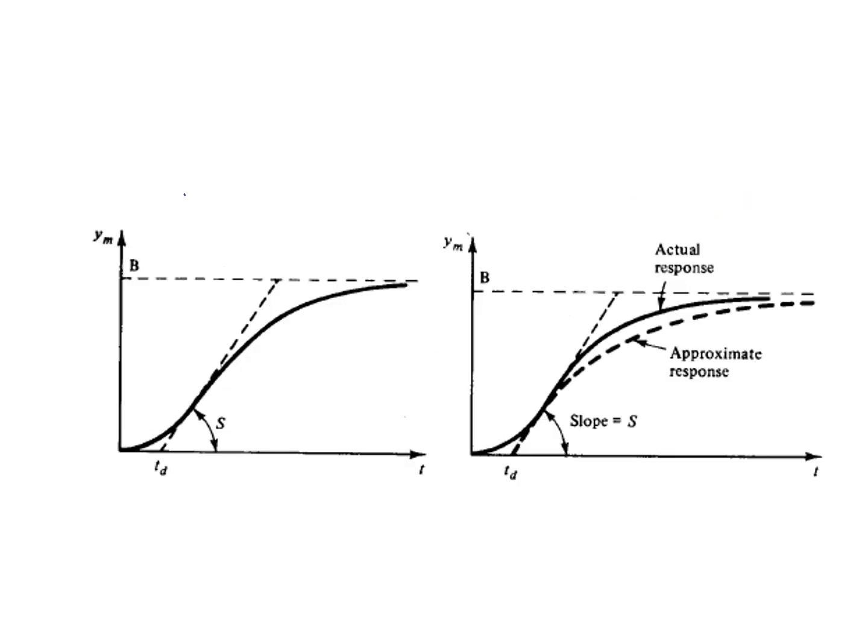So this is your PRC. When you break the loop between the controller and the final control element, introduce a step signal of magnitude A, which is A by S in Laplace transform, and observe the output, this is the output. Can you see this S-shaped sigmoid? This is called a sigmoidal curve. You have to draw a point of inflection line, and the point where that line touches the axis gives TD.